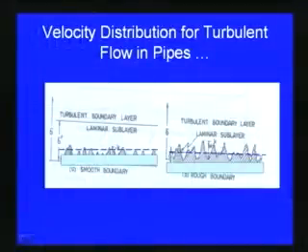That is why we are classifying the pipe as smooth boundary type and rough boundary type. In this slide you can see for smooth boundary, even though it is not perfectly smooth, there are small projections, but in comparison with the rough boundary, you can see that for the rough boundary case the roughness is too much. So, we classify this as rough boundary type pipe and the first one as smooth boundary pipe. Both will be considered with respect to the turbulent flow theories.